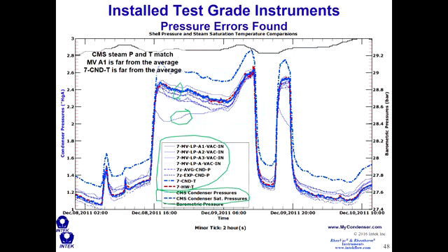And so what it turned out is that their alpha 1 pressure sensor was being affected by something in the condenser. I suspect it was, by the way, all of these measurements were not made 3 feet above the bundle. They were made much higher in the condenser, which is very common. So there's a location issue there. But this one here, I suspect, was located near a drain or some type of drain that was operated intermittently, causing its value to deviate like this.